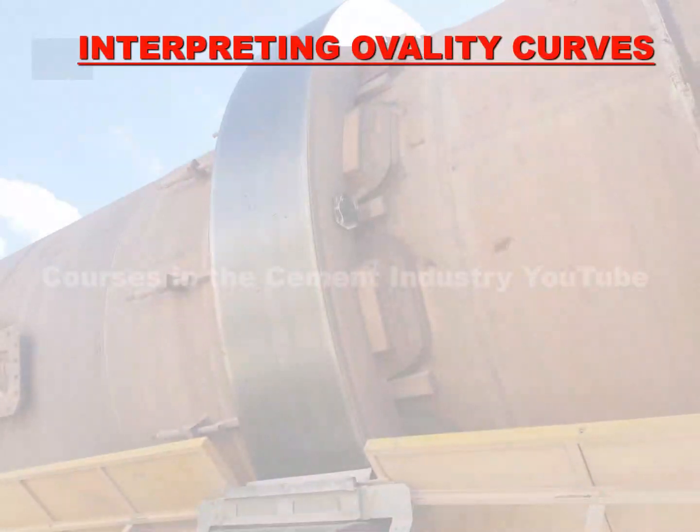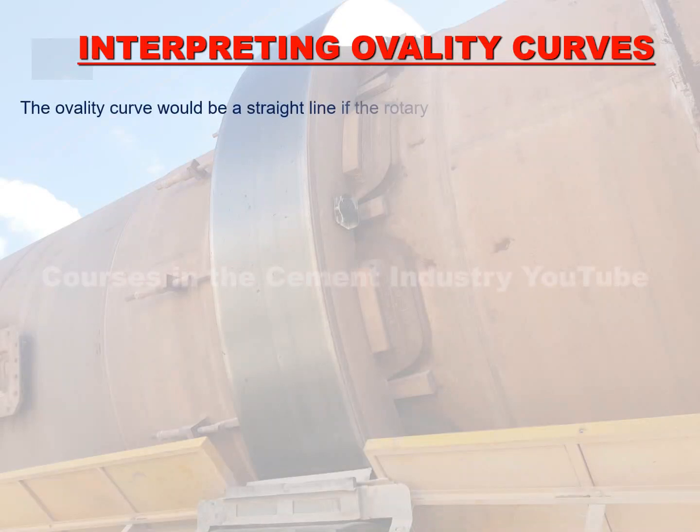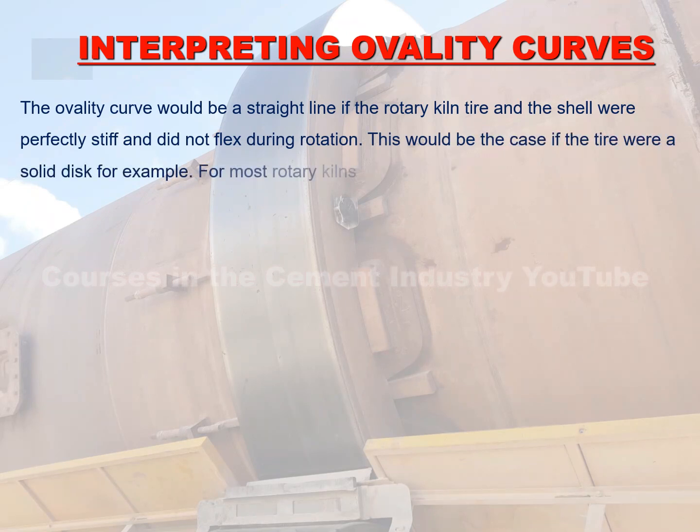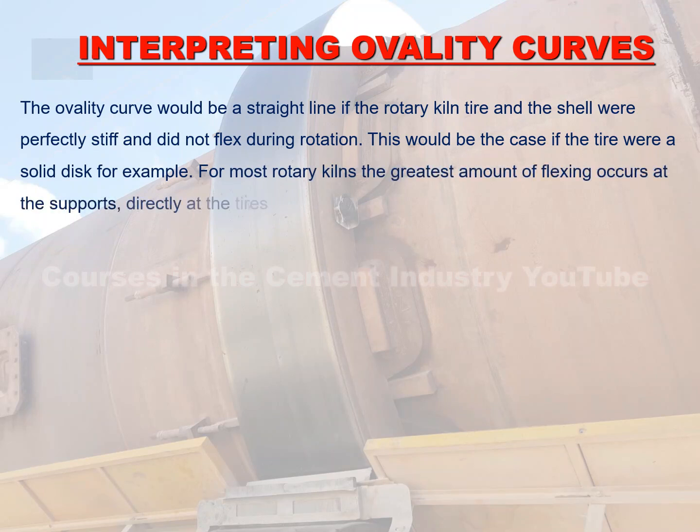Interpreting ovality curves. The ovality curve would be a straight line if the rotary kiln tire and the shell were perfectly stiff and did not flex during rotation. This would be the case if the tire were a solid disc, for example. For most rotary kilns, the greatest amount of flexing occurs at the supports, directly at the tires.